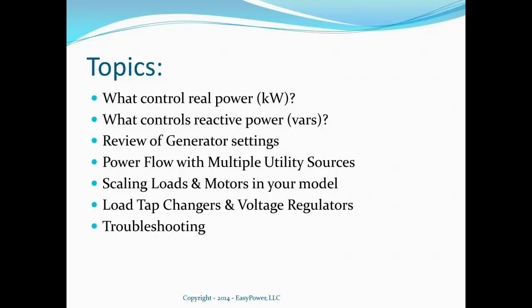And then we'll discuss a little bit about how to scale the loads and the motor loads in your model to get a realistic power flow, because I think we discussed last time, if you just use your connected load, you're not normally going to get a realistic power flow. You're going to have way too much load reflected in your system.